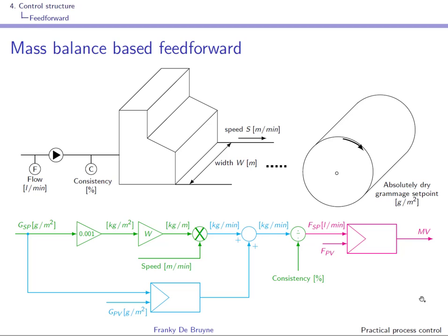In the control scheme that we have obtained so far, we see that a grammage set point change in the form of a step is going to be taken into account twice, once by the feed-forward mechanism and a second time by the feedback mechanism, right?